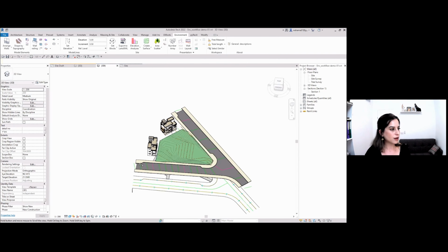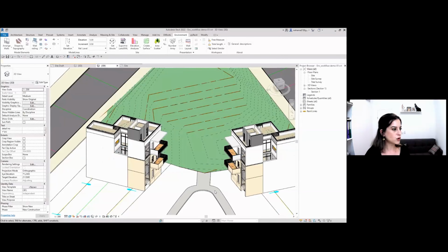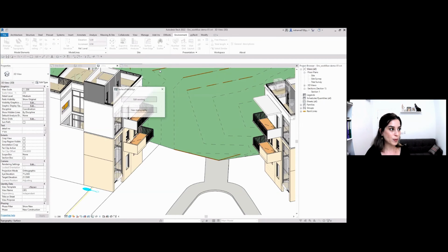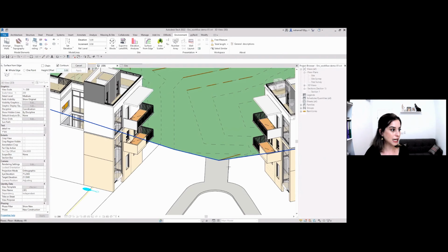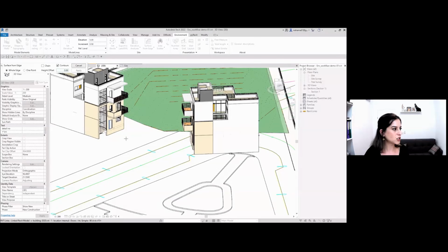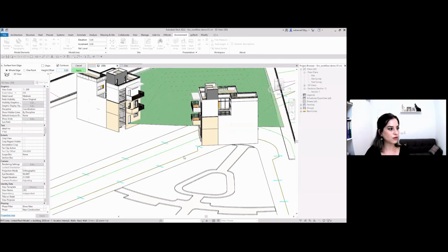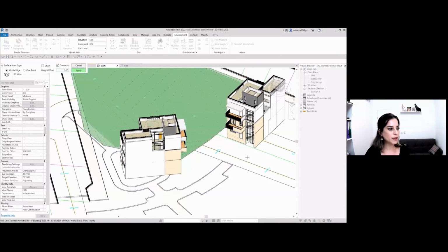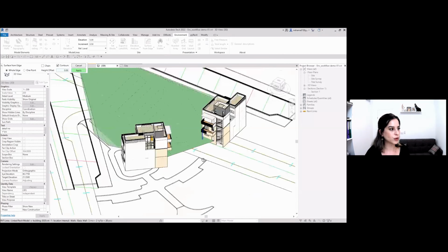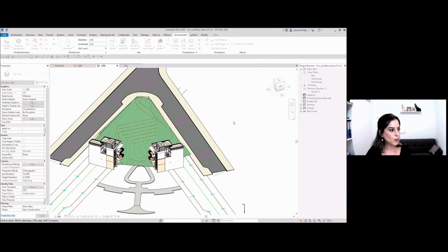And now I want to do another thing. I actually want my slopes to connect with the entrances to the architect building. So let's go again to surface from edge, edit existing, select this topography. And now I want you to see how nicely I can actually select the floor in the entrance to the linked file. So environment really makes it easier for us to collaborate with architects and road engineers using these tools. Let's click apply right now.